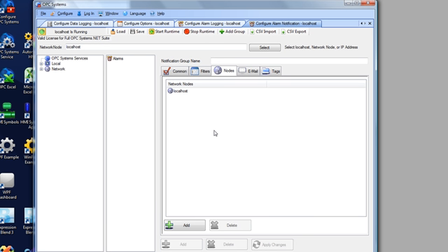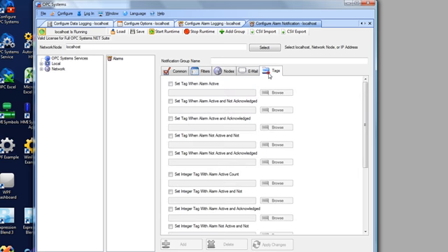However, if we're using the tags attribute to keep track of how long something's been in alarm or how many alarms have occurred over a particular time frame, this will always be accurate even if we have a temporary network loss. Of course, it's not available during the network downtime, but when the network comes back available, we will be able to have an accurate reading of all of this.